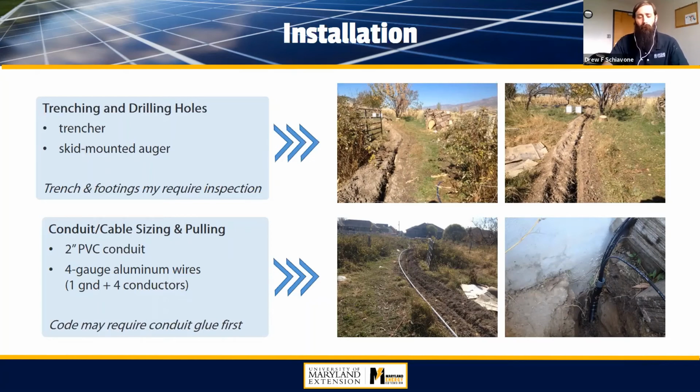They'll typically, again, this will be based on your local jurisdiction, but they may want to inspect the trench. In this case, it needs to be 18 inches in this example. So you need to get that dug to the proper depth, and they might come out and just inspect that. It'll take a minute or two. That's not too complicated. Some of the other permitting and code requirements are a little bit more sophisticated, but I'll highlight those. I'm not going to be able to touch on all of them, but I'll touch on a few aspects of that.